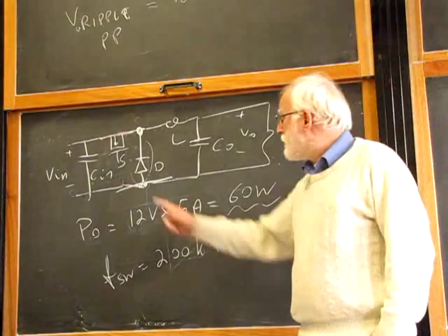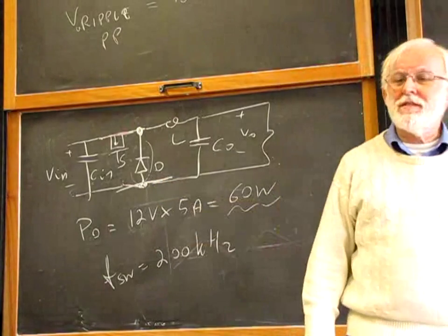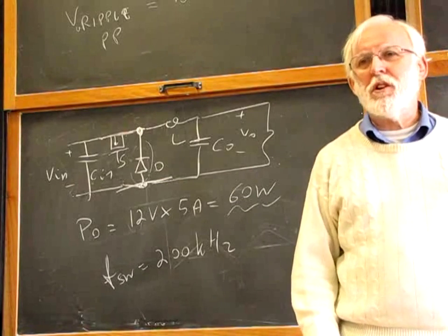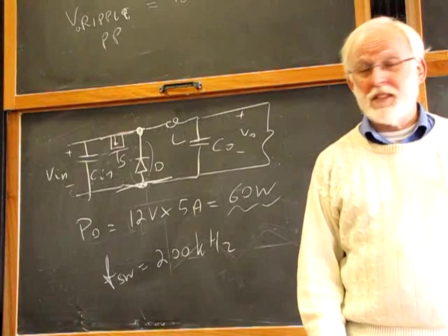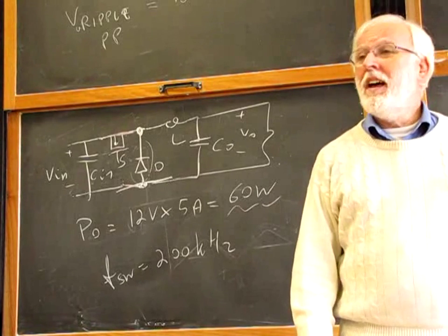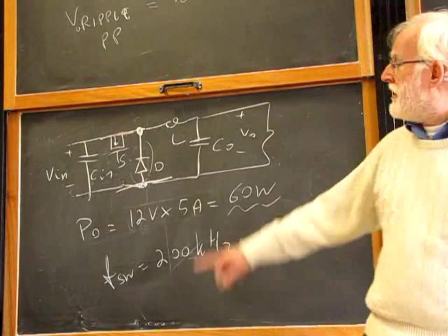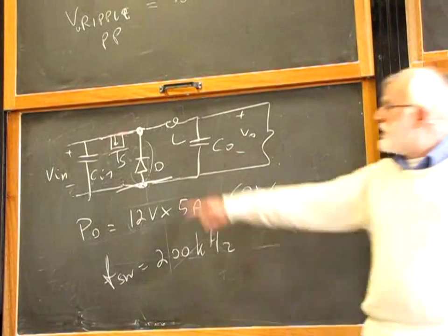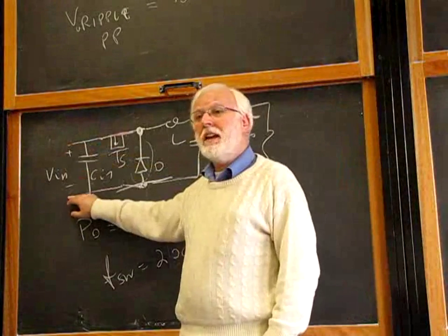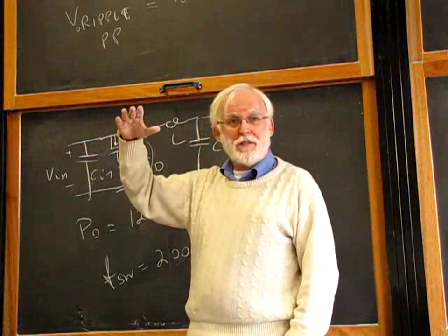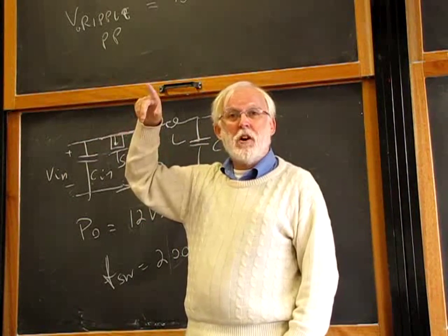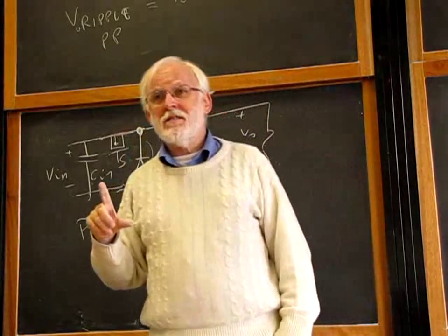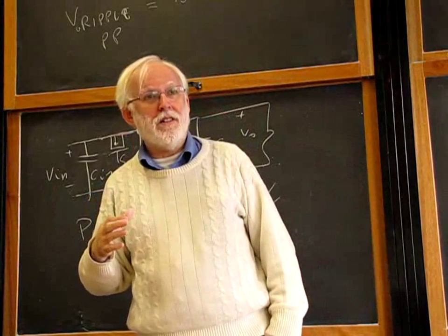Let's suppose you see a diode that has a rating of 40 volts. You take it? Yeah, should be okay. 40 volts, if the input voltage is maximum 28, it's okay. What if this goes in a car, in a truck, when the voltages over here are on average between 20 to 28 volts, but you can have spikes, over voltages of short duration, up to 50 volts, 80 volts or so.